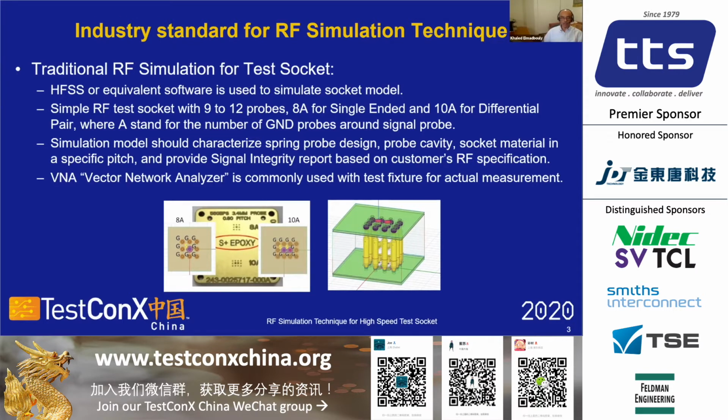However, this standard simulation is not good enough. When we design a probe head or a socket or a probe, we target a certain impedance, and matching this impedance is very important, but it's not good enough. What we need to do is match the impedance through the entire system, the test board and the device board, including the socket.